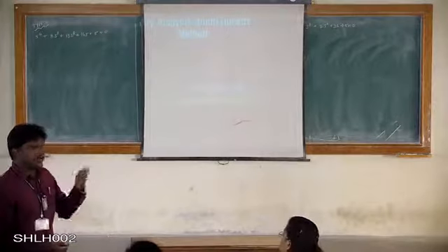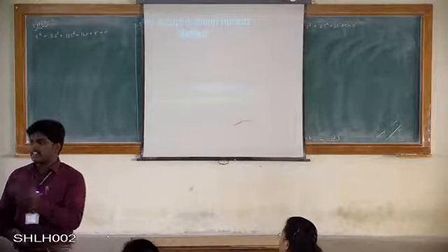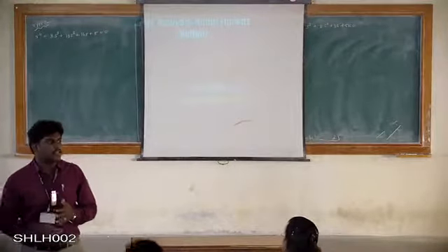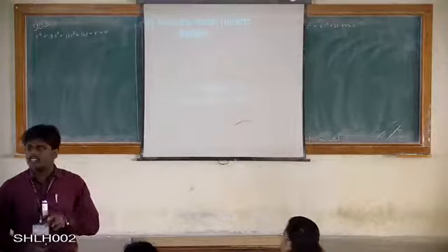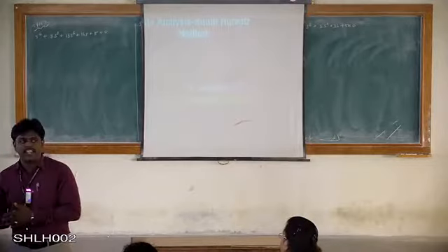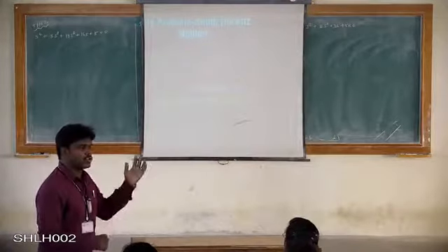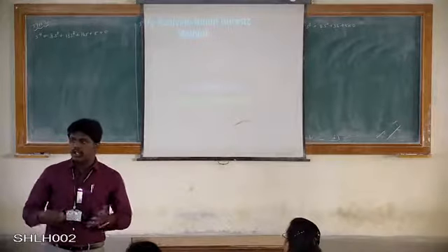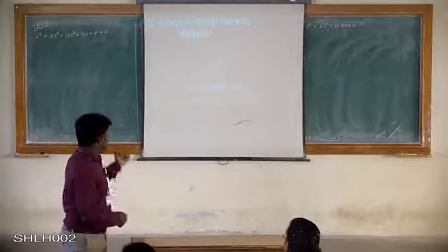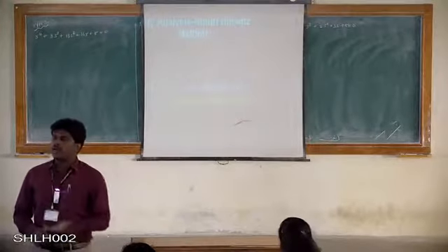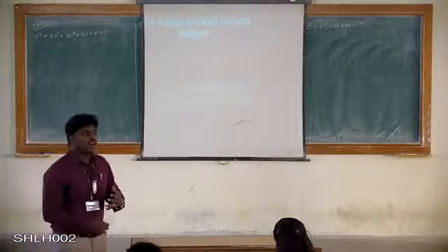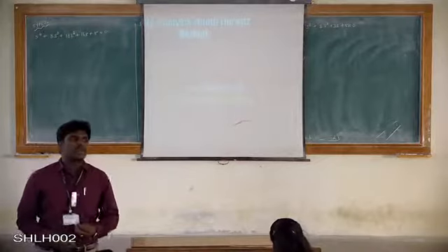Now, from that, we can do the simulation, because we use these methods for simulation purposes, to see whether the system is controllable or not, right? As well, we can check the stability analysis using theory methods. The Routh method is available, which is used for checking the stability, and the Bode plot and Nyquist plot are also available. These are the techniques that will analyze the stability of the system, right?